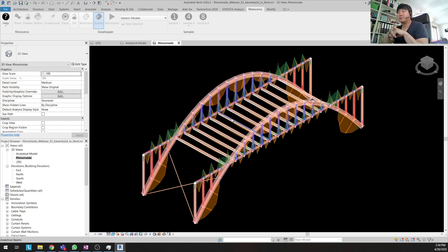But of course, if you have done this in your Grasshopper or Karamba script, this information can also then be fed into your Revit. And I guess has already shown, for example, how to create these beam elements, you have to then have the families already in Revit, for example. So you cannot just simply change the cross-section in Karamba and expect to have the geometry working for you in Revit natively. Is that correct? Yep.